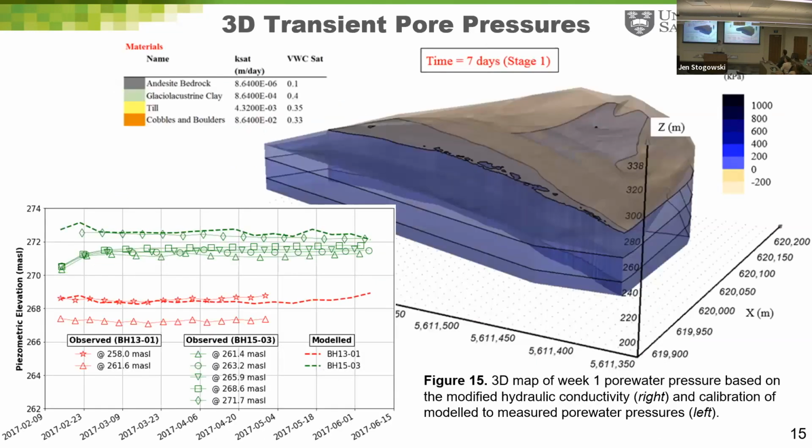So 2 transient pore pressure scenarios were modeled. The first case involved the seasonal increase in river level from minimum to maximum, while the second case maintained a static river level near the seasonal minimum. The purpose of running both scenarios was to isolate the impact of suction from river level, and this allowed me to quantify the contribution of suction to slope stabilization, or equivalently the initial slope destabilization.